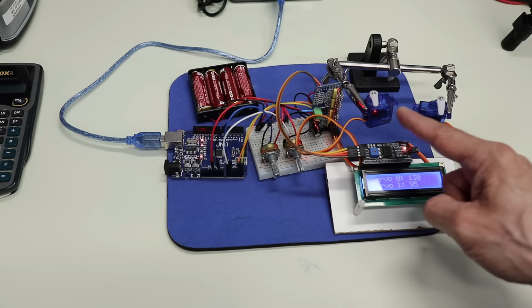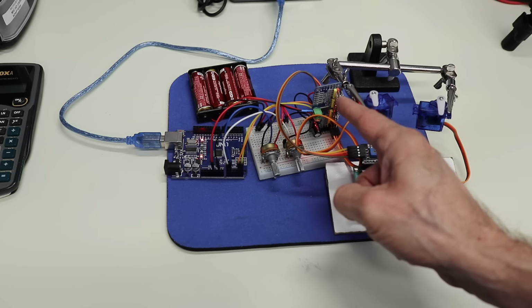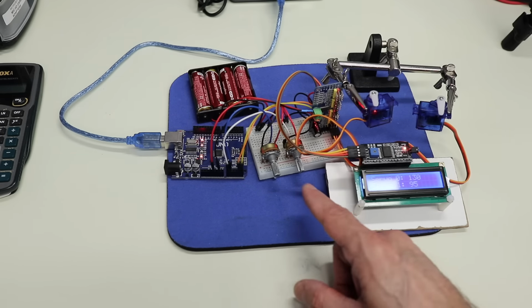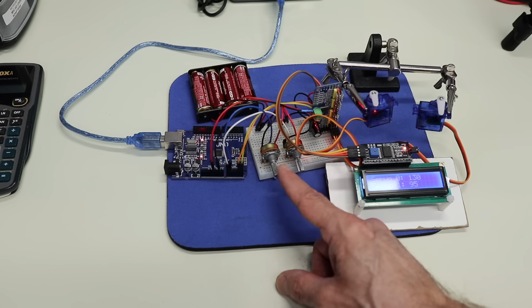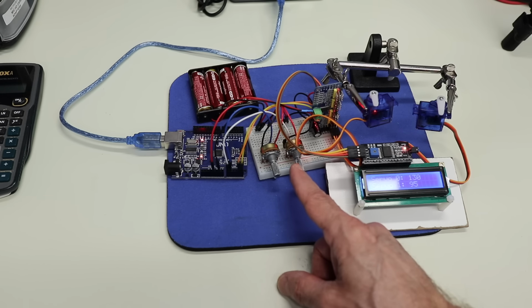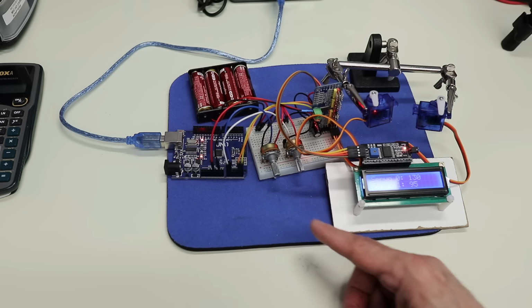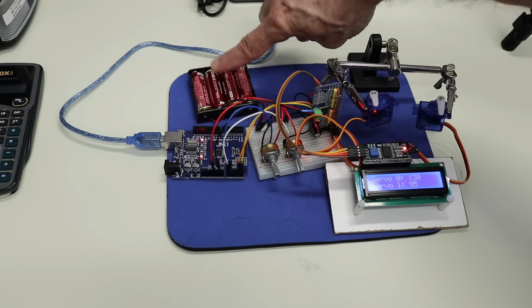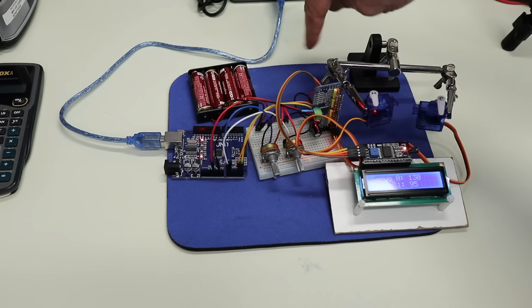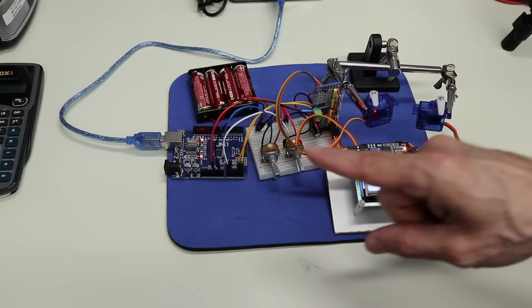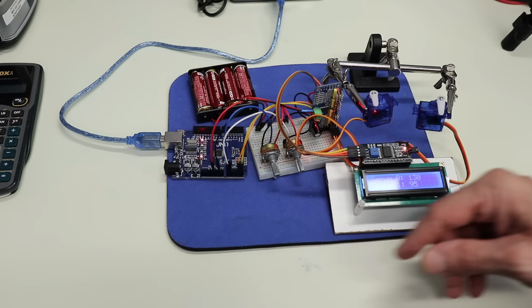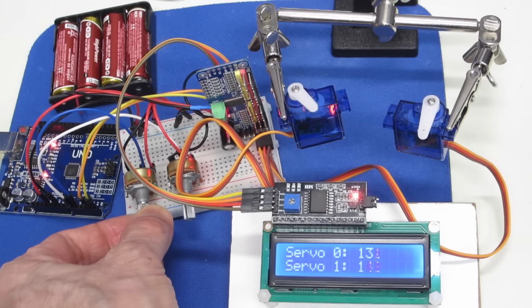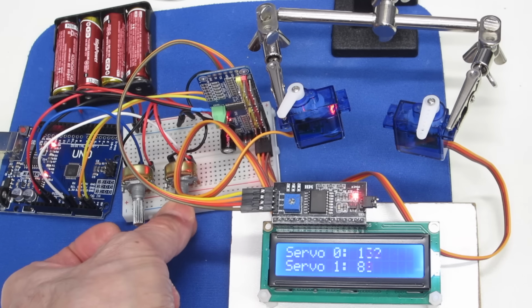Now here, of course, are my two servo motors, and here's the PCA9685 I'm using to drive them on this little solderless breadboard. You'll also see the two potentiometers that I'm using in order to control the motors. Now for my power for the motors, I'm just using these 4 AA cells over here. So I've got a 6-volt battery over here to power it, and that's a good power source for servos. And of course you can see my Arduino Uno over here. Now I've loaded the code, so all we need to do is watch it work, and I'll twist it and I can move the servos.